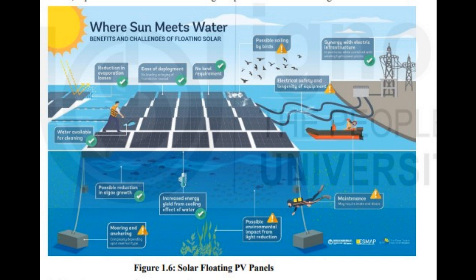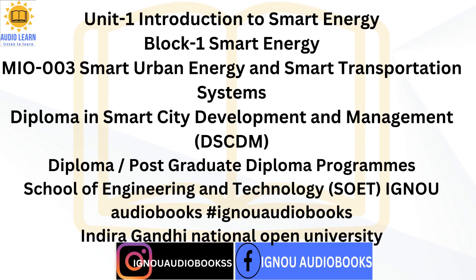1.6.2 Disadvantages of floating solar. Costs. When compared to more typical forms of solar panel installations, floating solar systems may incur higher expenditures. As it is a new technology, it requires more skilled knowledge for installation than installing similar-sized solar farms on rooftops or ground. Applications. Floating solar systems don't work for everyone. The vast majority of floating solar systems are large-scale, providing power to utility companies, big towns, enterprises, and municipalities. If you are looking for solar power for your home, then it makes a lot more sense to install a system on the roof or on the ground.